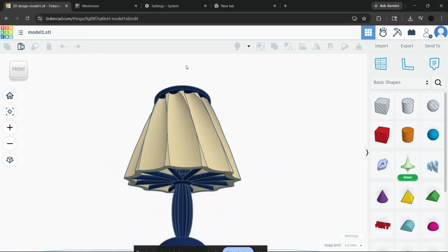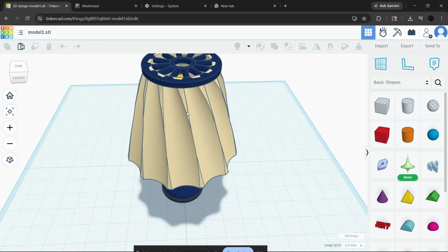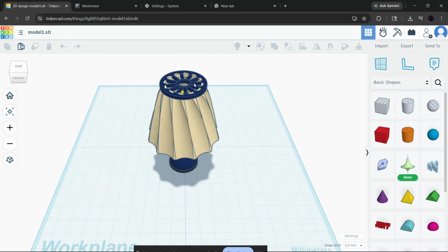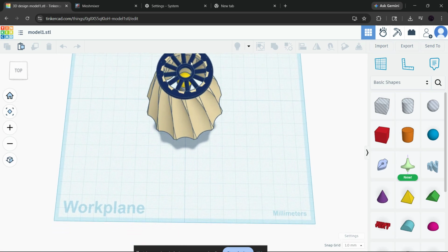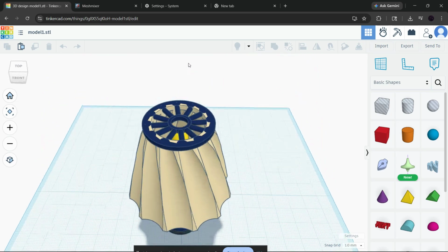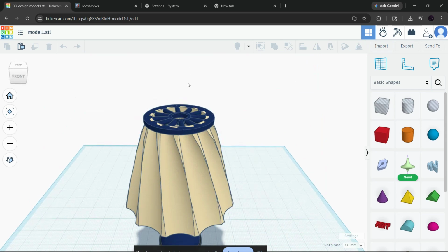If you prefer Blender, try adding a decimate modifier to reduce the triangle count, especially if the model is extremely detailed. As a general rule, aim to keep it under 100,000 triangles if possible, then export it again as a binary STL for better compatibility.